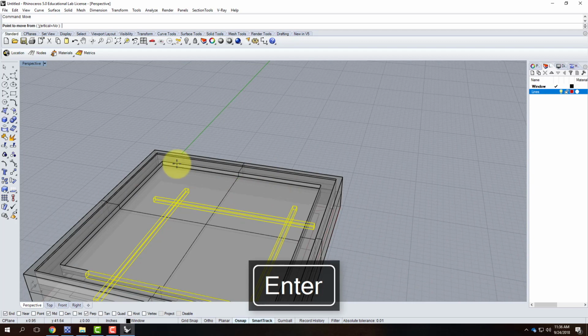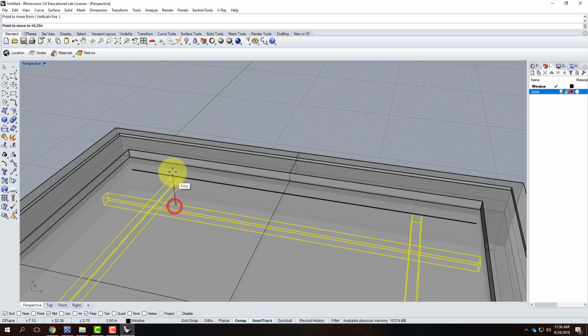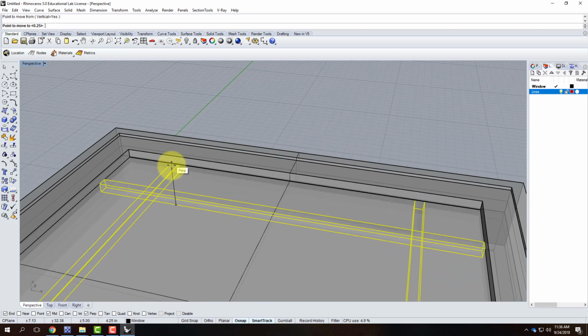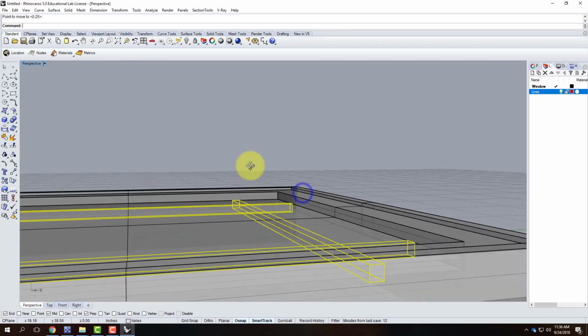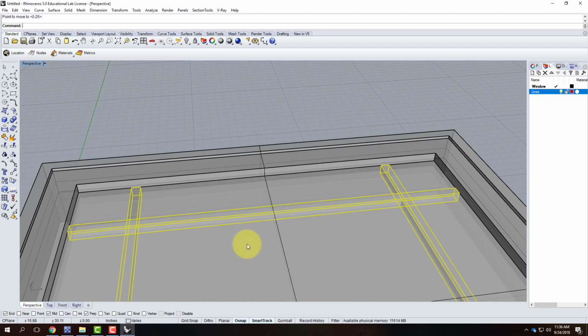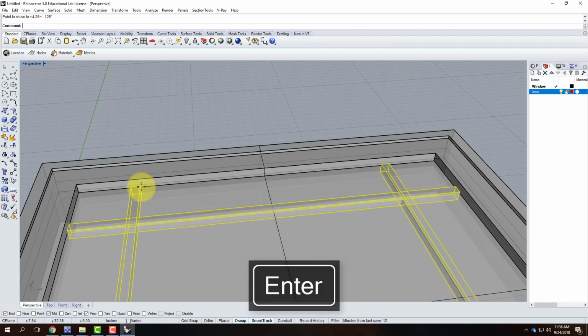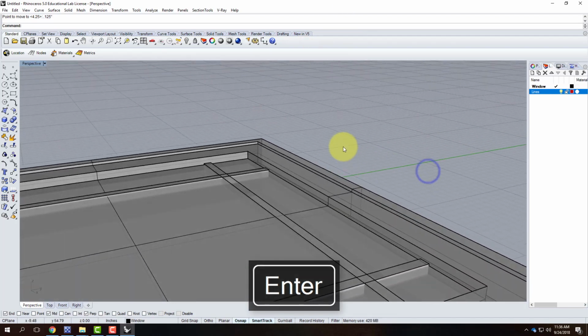We go to move. This is going to be another vertical move, so I'll click on vertical or type V for vertical. And we'll move this up until it touches that top surface. There it is. Notice I have perpendicular snap, so it moves straight up and stops at that point. That's good, but these need to go up just a little bit higher. I made these 3/4 of an inch. I made the glass 1/2 an inch, so they need to go up by 1/8. So I'd move vertical again, and this would be 0.125, so that they stick out just a little bit.